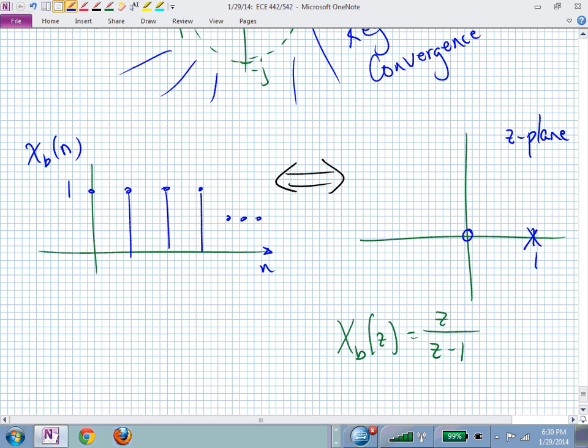It's going to go unbounded, isn't it? Just like if you applied a unit step in continuous time, a 1 over s, to an integrator, which is 1 over s, you have 1 over s times 1 over s, which gives you 1 over s squared, whose inverse Laplace transform is t, and that's just going unbounded. And this is consistent with that observation.